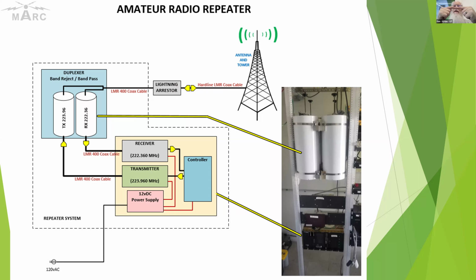So in the lightning arrestor, you have the line, the center conductor, and then you have another conductor that is tied to ground. When a lightning bolt hits, this arcs and it goes to ground. Okay. It's easier if I drew it on the board, but no one can see it, so you just have to trust me.